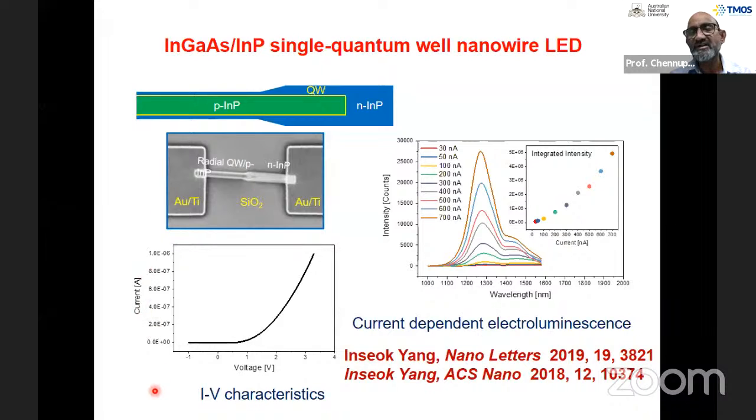and he started pumping current and looking at the IV characteristics here. You can see the current-voltage characteristics show diode-like behavior, indicating that he's able to make this PN junction, get ohmic contacts, and make a PN junction with diode-like behavior here.